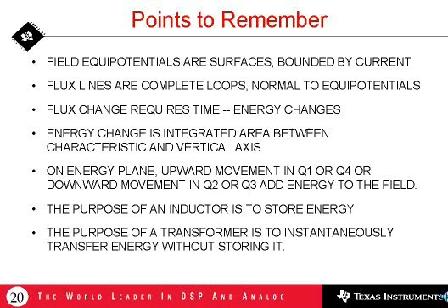On the other hand, flux lines are considered conceptually as lines. They are complete loops. They don't begin, they don't end, and those flux lines are normal to the equipotential surfaces. To change the flux requires time. And this is part of the aspect of energy that's involved here. Time is involved with energy, and time is specifically involved with changing flux. And this becomes more apparent with Faraday's law, which shows that the flux depends on the integral volt-seconds.